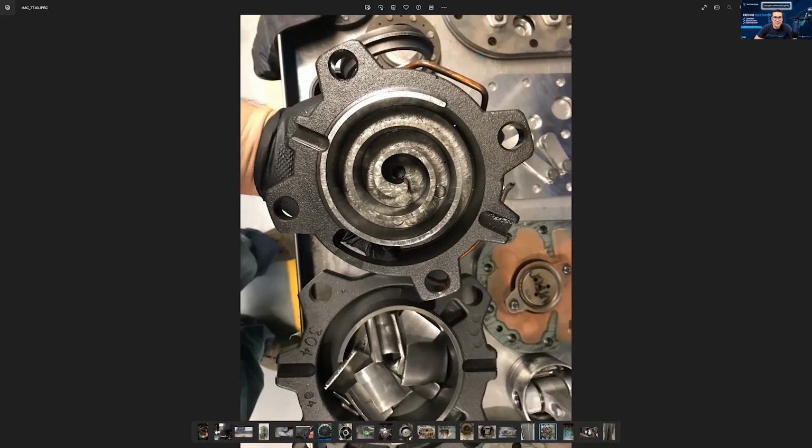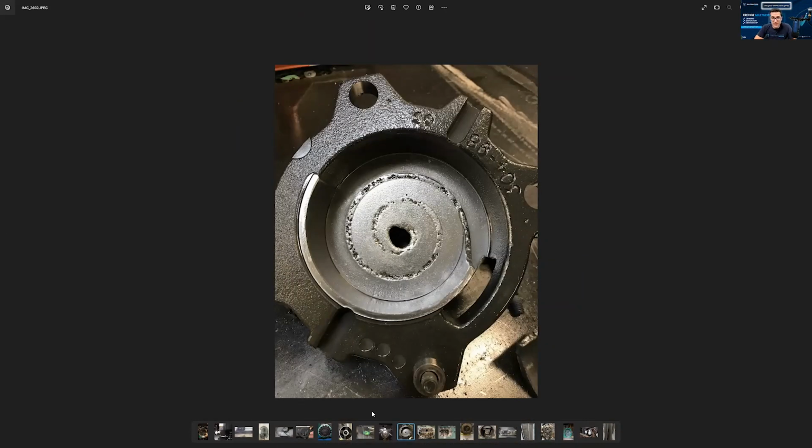And so this is important, what you need to look for, right? You need to look for this in semi-hermetics. You've got to pull the compressor apart to find it. And it's no different in scrolls to figure out the failure, because that compressor could have had an electrical failure. Could have been still running, maybe. You don't know. What'll happen if you're having these flooded starts, liquid migration going back, is that all of a sudden there's a massive explosion washing all that oil away and potentially metal on metal.